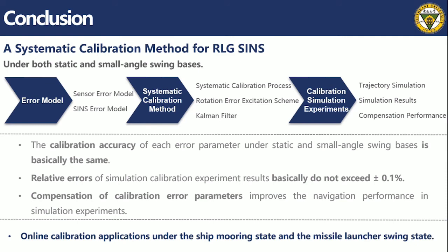Then, multi-position rotation error excitation scheme is introduced to excite errors under static and small angle swing basis. Besides, a 33-dimensional Kalman filter is designed to estimate error parameters.